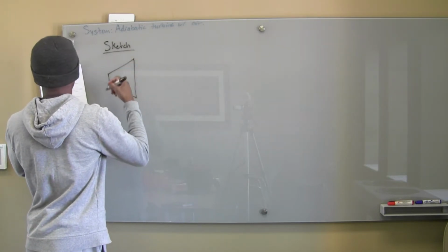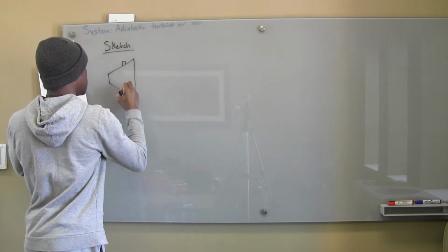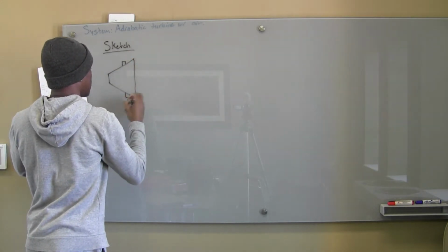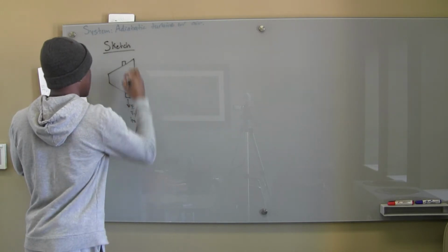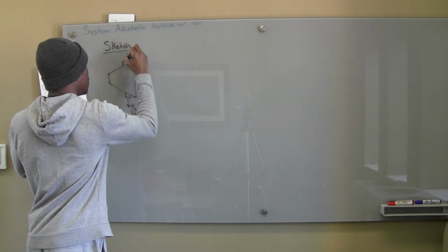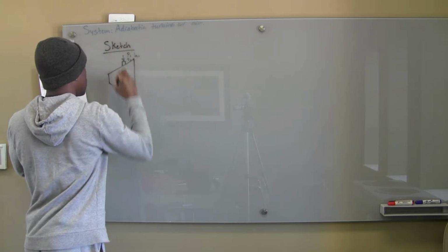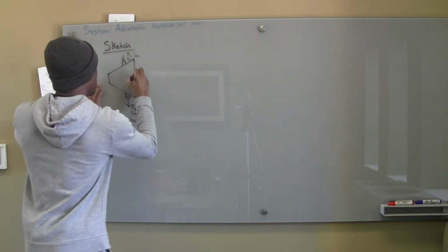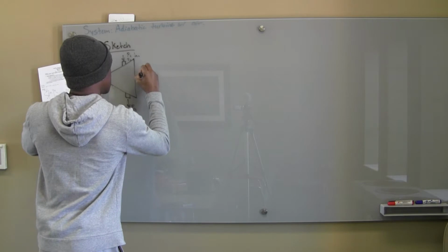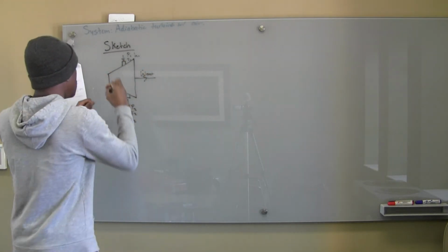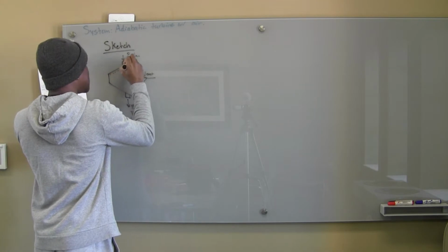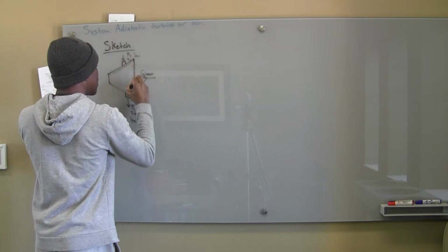Alright, something like this. So we're going to have our P2, T2, H2, right? P1, T1, H1. And it's going like that, right? Then we're also going to have work out because it's a turbine, right? Work dot, power. And then what you can also do is just draw like this to just imply that that's our system that we're looking at, right?